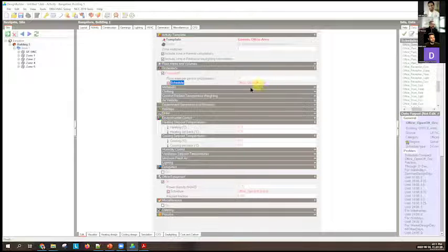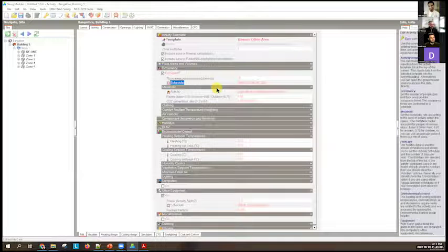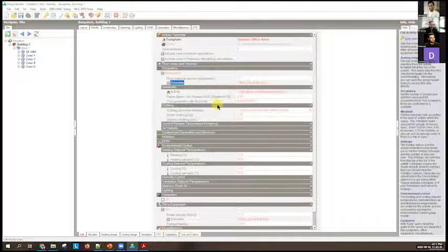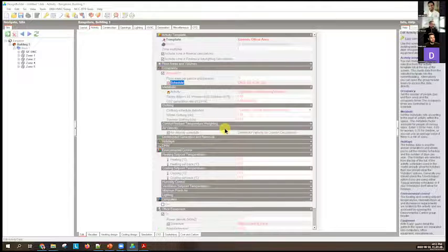Then there's a schedule for how the building is occupied, a profile of how people come in and leave. There's something about metabolic rates: how much heat are you producing? What kind of clothes are you wearing? What's the air velocity in the room? Typically, if it's an air-conditioned room, there's barely any air velocity, and I think the default is 0.137 meters per second. That's definitely something taken from the old imperial system.